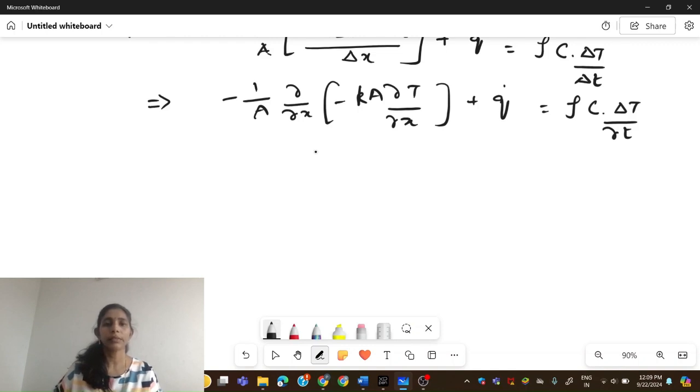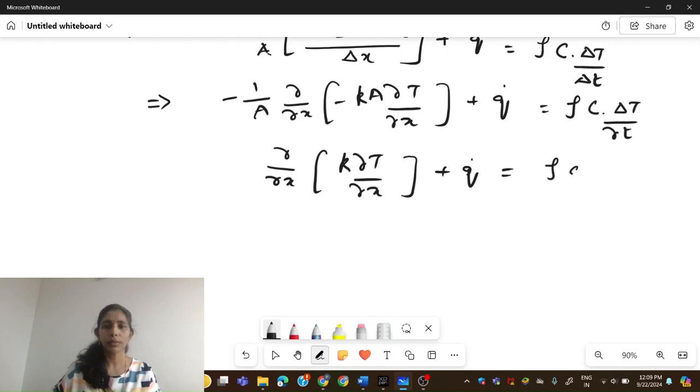Now the negative and negative will cancel, A and A will cancel, so we will get dou by dou x of K into dou T by dou x, plus Q dot, this is heat generation, equal to rho C dou T by dou t.